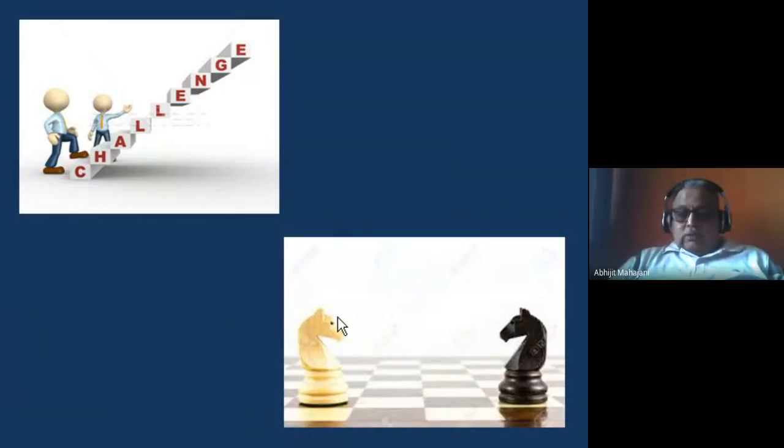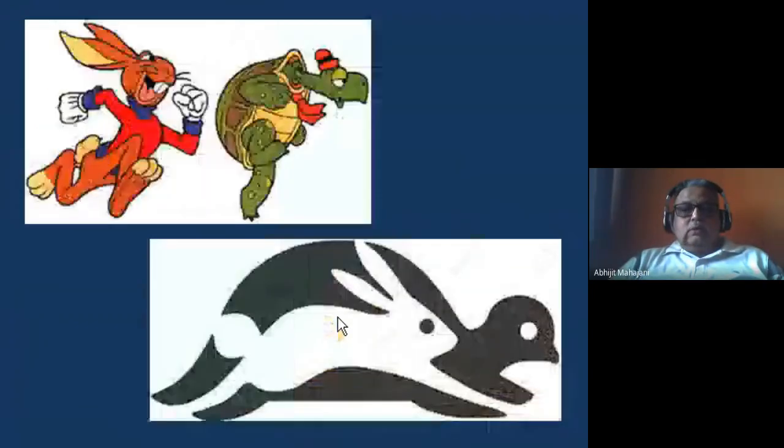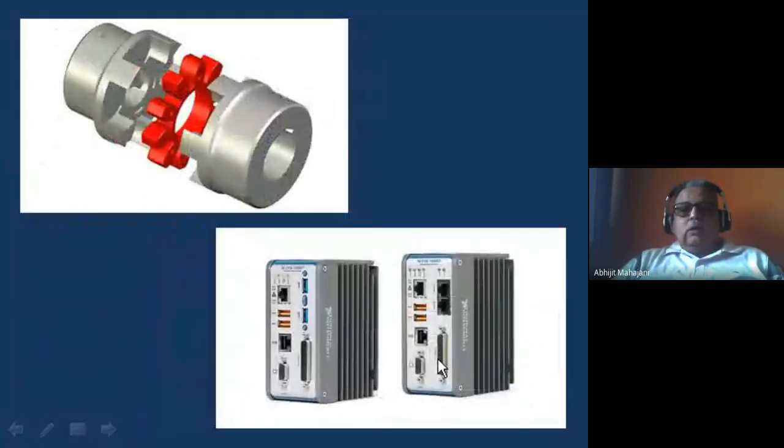How do we overcome this challenge? This challenge is basically, as I said, because the protocols have different speeds. The protocols from OT are very fast. The protocol from IT is a slow protocol. Now the crux is to manage the speeds of them together. And how do you do that? I showed you in the earlier Industry 4.0 slides that there is something called an edge node device.